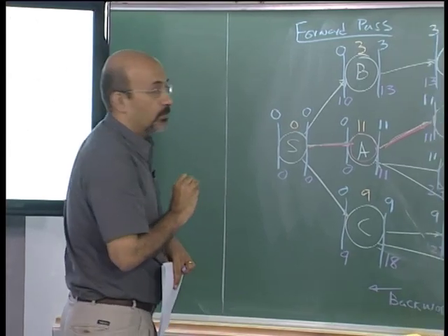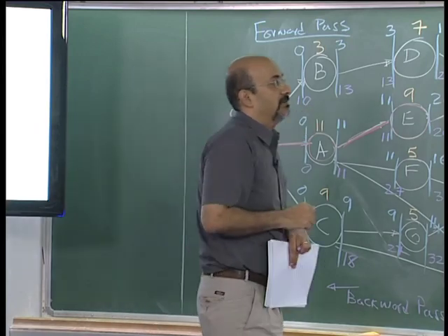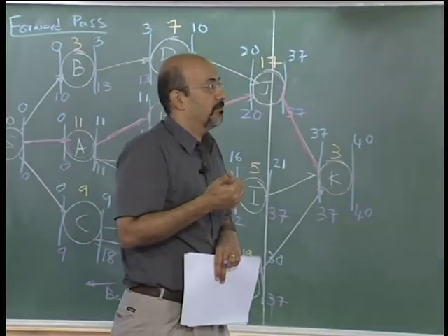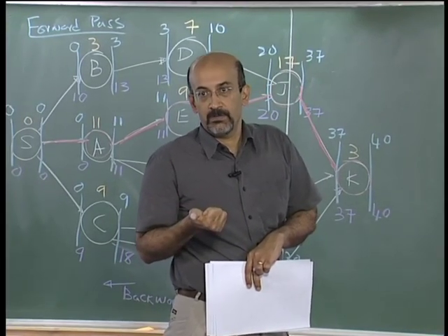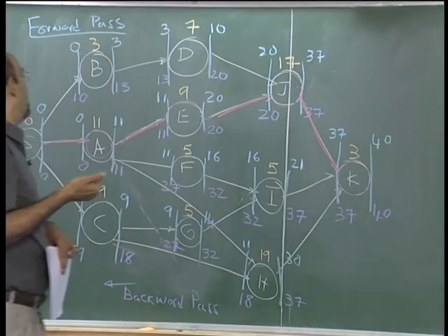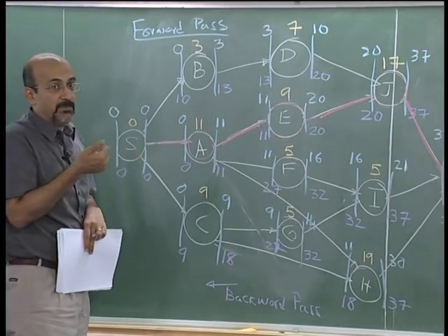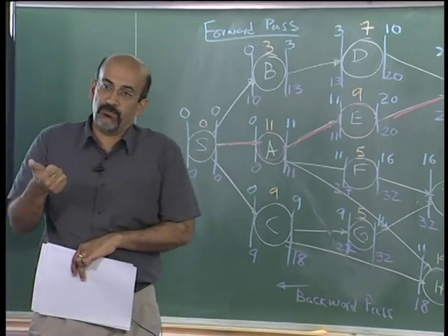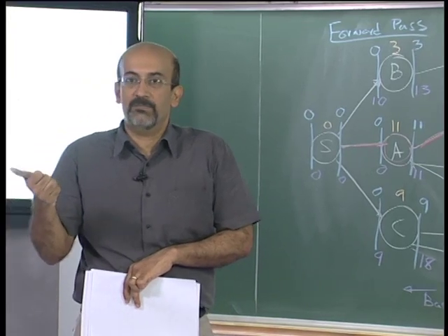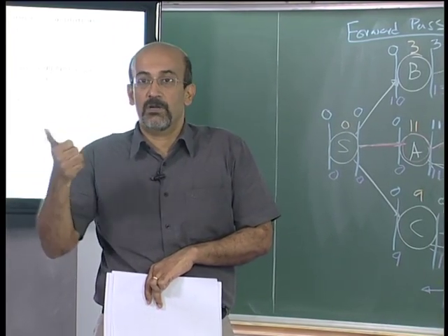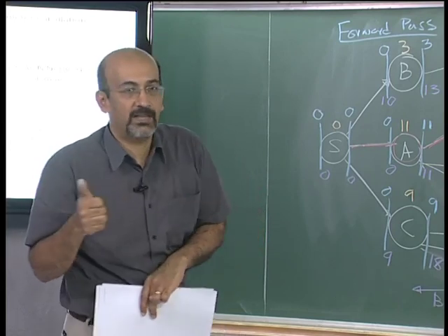Now we come to the floats. Remember, how many floats do we have to calculate? We have total float, free float, interfering float and independent float. So we have 4 floats. In a network like this it might still be possible to visualize especially total float and free float, but interfering float is a little more difficult to visualize, though easy to calculate.